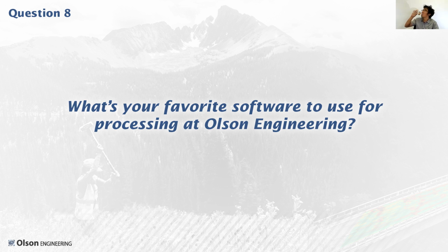Okay. What's your favorite software to use for processing at Olson Engineering? For 2D refraction, we use Refract, and this is the one that uses the wavepath eikonal travel time method. I don't like it just because it uses that method. I find that it gives you a lot of options for choosing your initial model, and like I said, the initial model is probably the most important thing. So that software, because of its ease of generating initial models, is generally my favorite.